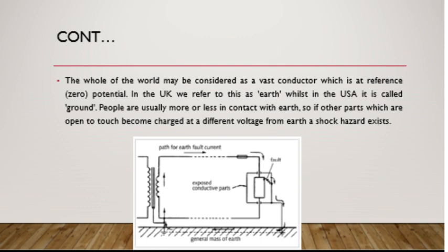But at the time of normal current it offers a high amount of resistance. So it should be designed such that earthing comes into the picture only when a high amount of current is flowing, or there is a fault path available.